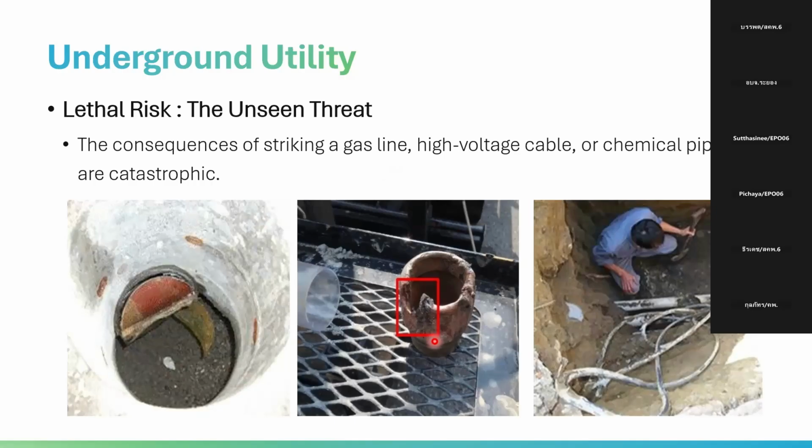It's very, very dangerous. And when we used the hollow stem auger to install a monitoring well, even though we did not get close to the wire line, the hollow stem auger is much bigger and it rotates underground, so the wire line was pulled out from its plastic pipe. So it also caused very severe issues. So it is important when you are doing soil sampling or groundwater sampling at a site in a factory.